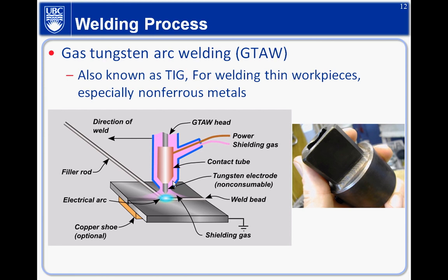Okay. TIG weld, the gas tungsten arc weld. This one uses a non-consumable electrode. Basically the electrode here is tungsten. There is shielding gas coming from here. Then your filler material, or filler rod, is a separate stick. You can hold a gun here and hold the filler rod in the other hand, and as you go along this weld here, right?